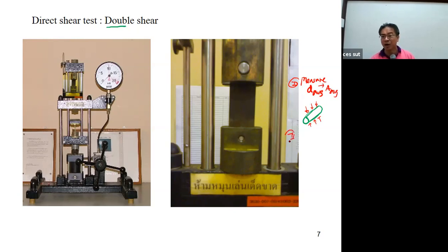And then the second one, I would like you to weigh the specimen. And when you weigh the specimen, you also need to measure the length. Okay, you just compute the density of each specimen. It must be aluminum, brass, and copper, and you just divide the weight of aluminum by the volume of aluminum. I would like you guys to determine this. This second step is the new one. We didn't do it for the previous one.